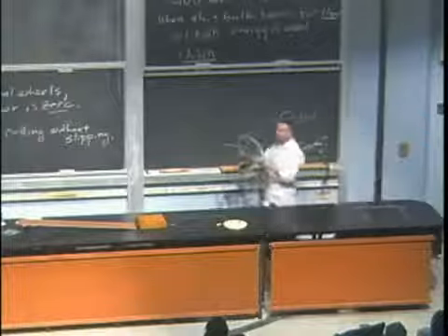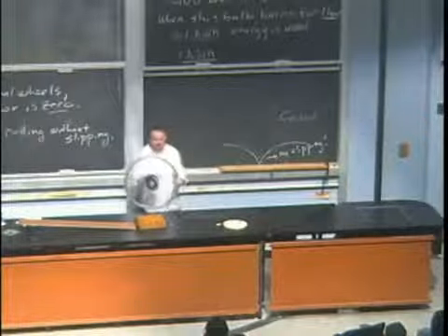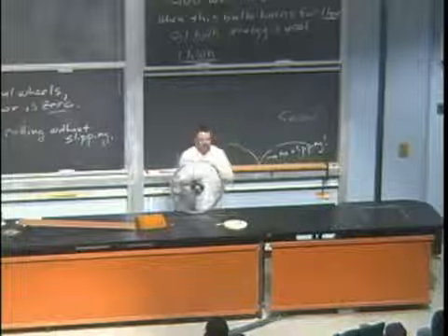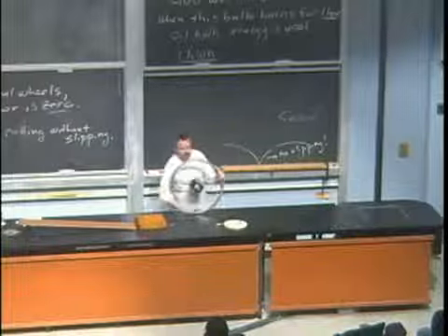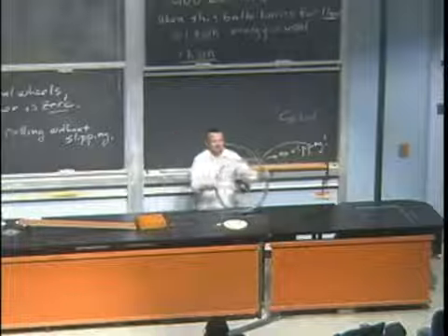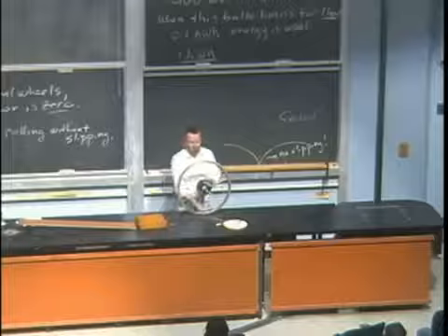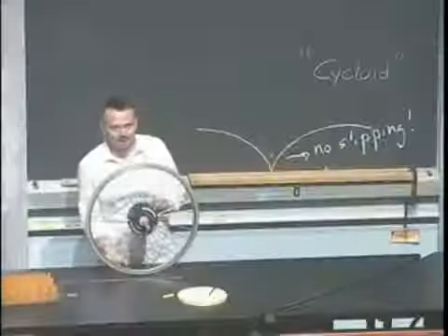So why does it start rolling? We come down, it's got relative motion, so when it touches, there is slipping here. That wheel is trying to slip over the surface. The fact that it's slipping means that there's friction. That friction is acting backwards.